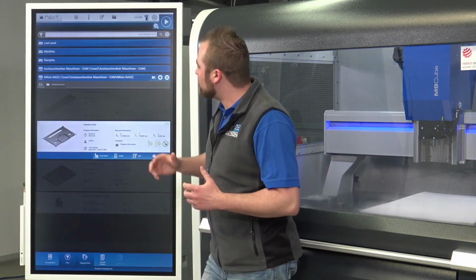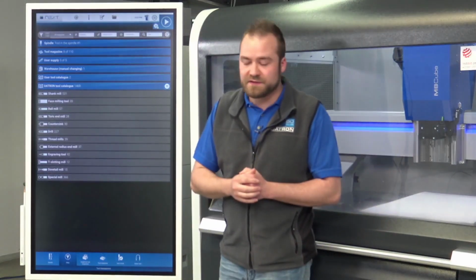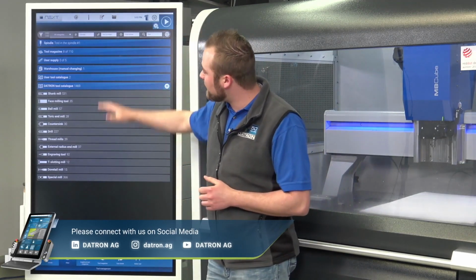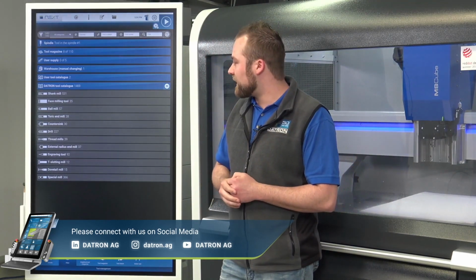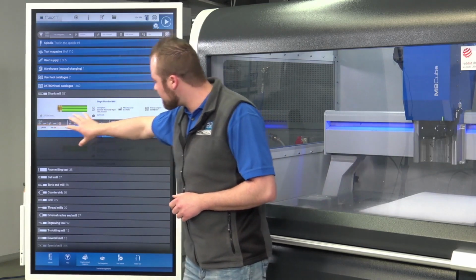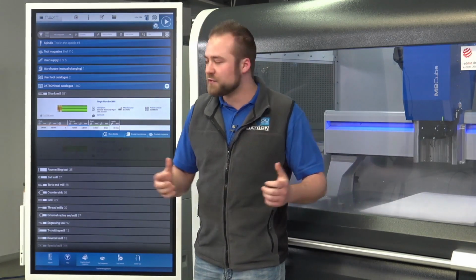What we want to take a look at second is the tool management. You don't have to use the tool check by the program, you can also check your tools with the tool management button. Here you can see all the tools that are inside of the machine. But you also have the Datron tool catalog, where you can find every tool and take a look. If we tap on a single flute, we can see a lot of information about the tool, and we can also set up these tools inside of the machine.